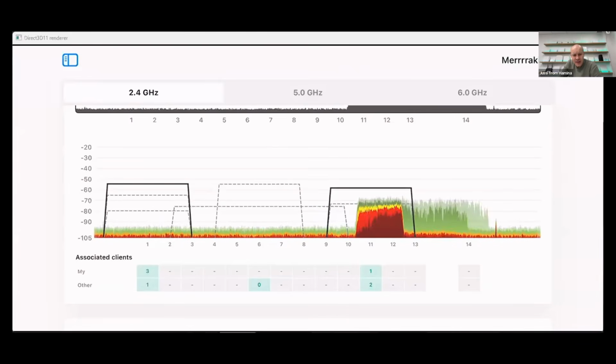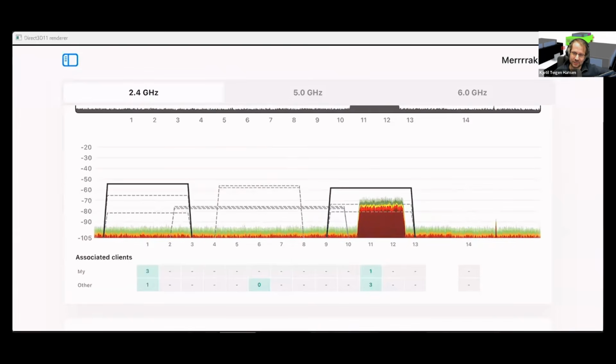But I use it for testing other analyzers. Even though you have that high utilization on the channel, like in the middle of channel 11, the AP on channel 11, the beacons are still there. The best thing you can get for yourself is a really good old USB 2 cable. If you need to connect to your chamber, get a proper thick, 5 meter long USB 2 cable, because that doesn't interfere. I used a USB 3 cable, and the whole chamber got so much noise.